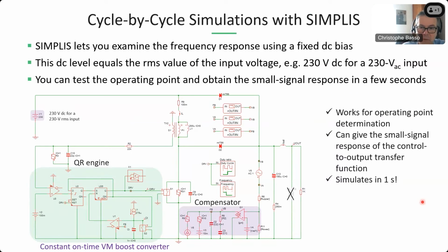In this example, we can see a 140 watt boost converter, which is operating in critical conduction mode. You can find also in the literature boundary BCM type of power factor corrector. So the part requires here the sensing of the magnetizing state of the inductor via an auxiliary winding, which is here, because we wait that the magnetization is complete before starting a new switching cycle.